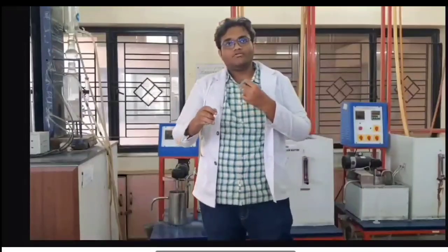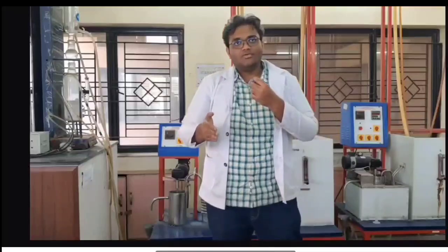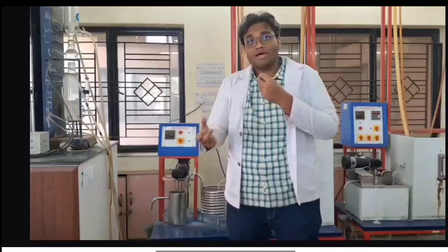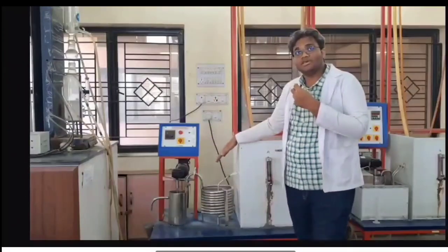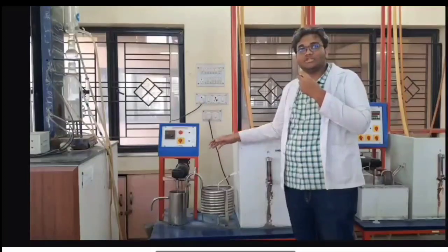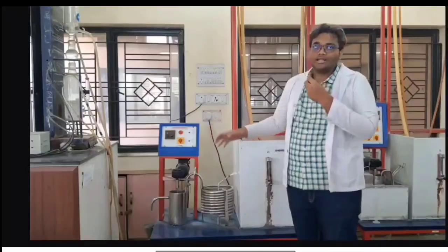Now, titrating the PFR sample. We'll take 20 ml of the sample from the PFR and repeat the titration steps. By comparing the results of CSTR and PFR, we'll get insights into how the dynamic influence of the reactions are playing out.